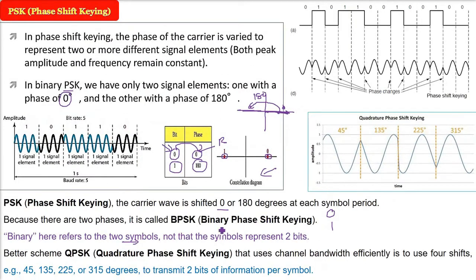So I was telling you about QPSK. Now again going to the Cartesian coordinate system. So 0 and 180 degrees we saw. Now let us make a line here in between. We can represent 4 angles because the waves have different angles, 0 to 360 degrees. So you can represent 45 degrees from the x-axis. This angle is 135 degrees. This angle from the positive x-axis is 225 and this whole angle is 315 degrees.